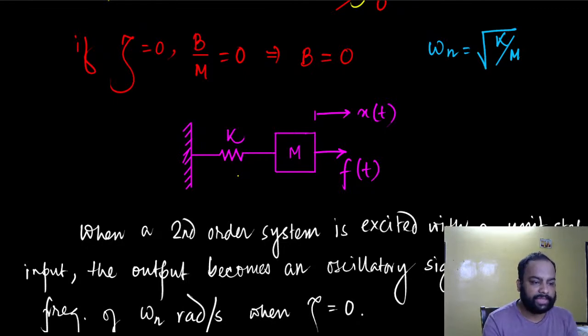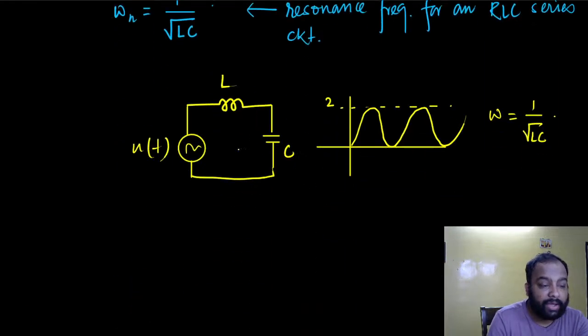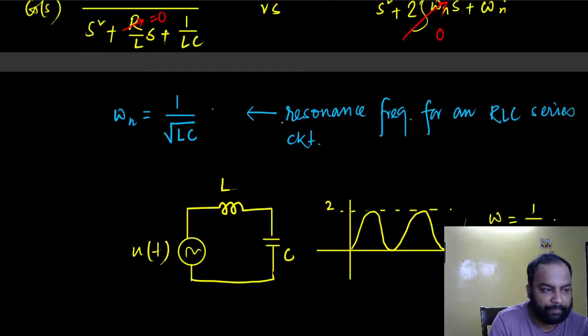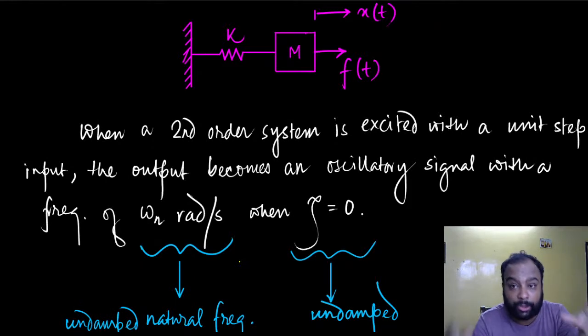Here in this circuit, in one cycle the capacitor gets stored with energy, and then in the next part of the cycle that energy is released and stored by the inductor. Then the inductor releases the energy, which is stored in the capacitor again, and that keeps on happening. Since there is no resistor here, there will be no copper loss, so there won't be any I square R loss. That I square R loss would have reduced the total energy content in the system, but since it is not there, the energy is never spent.